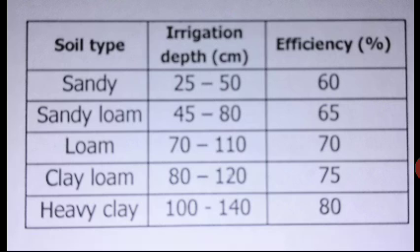Next is crop ratio. Crop ratio is the ratio of areas under crops to two main seasons. The crop ratio is selected in such a manner that the discharge requirement of the canal supplying irrigation water for both crops may be nearly the same so that the canal section is put to the most efficient use.